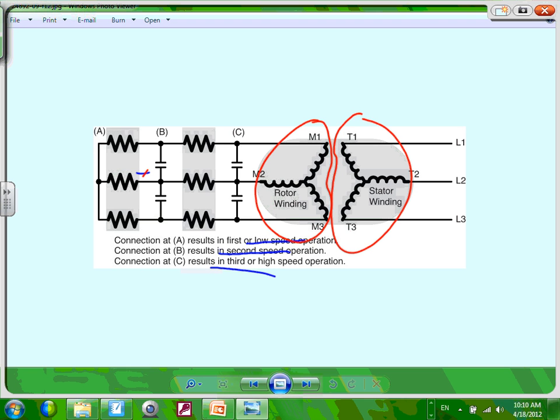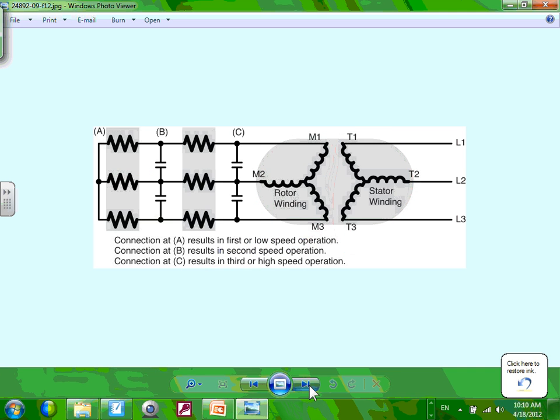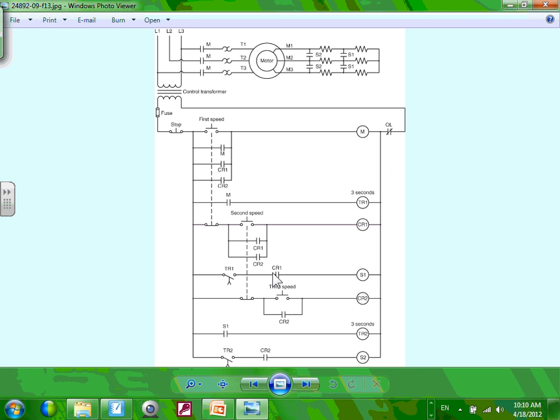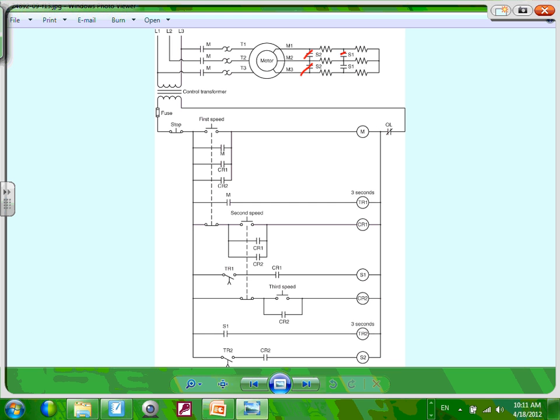So with the advantage of VFDs right now, VFDs have made induction motors more superior. Here's how they control, guys, the wound rotor motors. Here's a controller that can get you 3 speeds by very easily closing these contacts and opening some and closing some through this control system that I'm not going to walk you through. Any comments, guys? If you hear wound rotor motor, think old fashion speed control. That's all you want to remember.